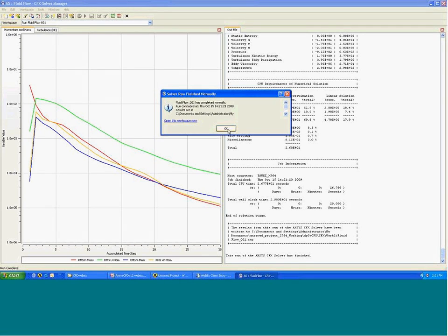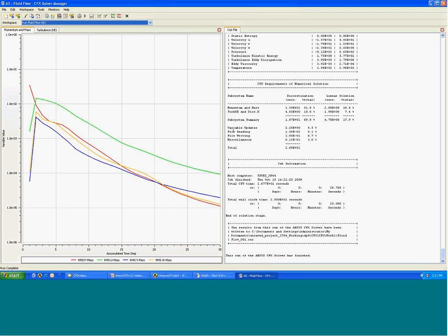And we'll treat that as a steady-state solution having been established. In this domain, the overall element count is roughly about 30,000. And I can converge the solution in less than 30 seconds, which provides a very good preview of what is happening in the external and the internal flow field of the probe.